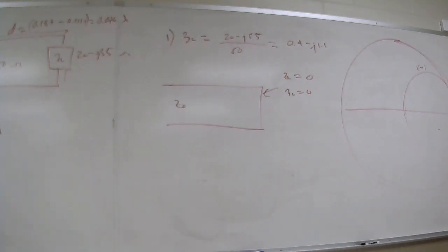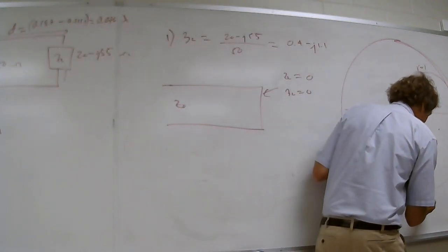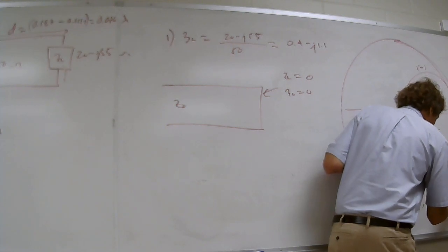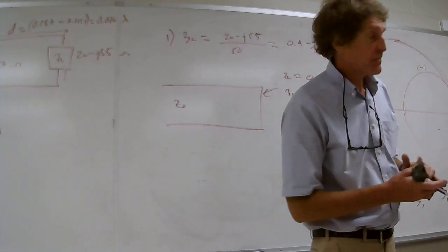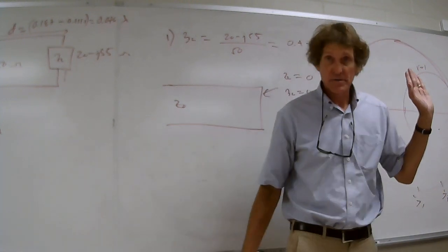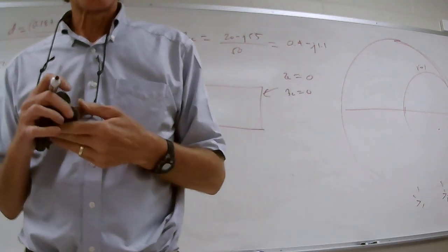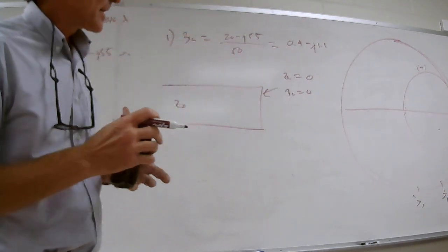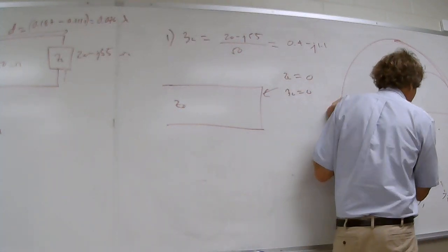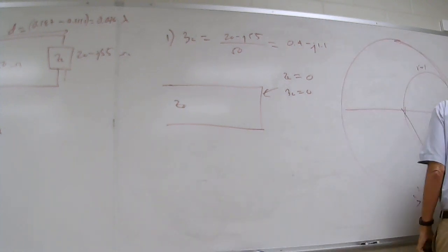Can you all hear me? Where's that? I'm going to guess if this is minus J1, it's about here. This is going to be minus J2. And there are no negatives there. Everything in the southern hemisphere, that's reactance down here, they're all negative values. And the upper part's all positive J. With me, class? All right. Now, take your straight edge and draw a line right through there. And tell me what you get for wavelengths towards generator.